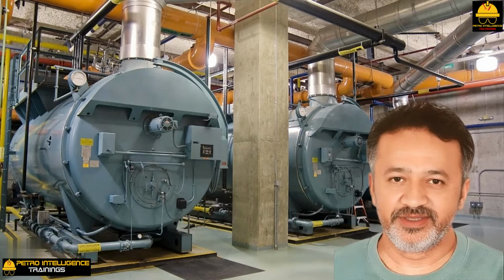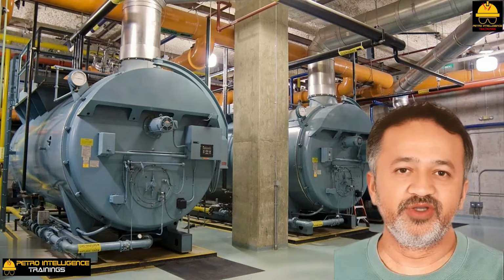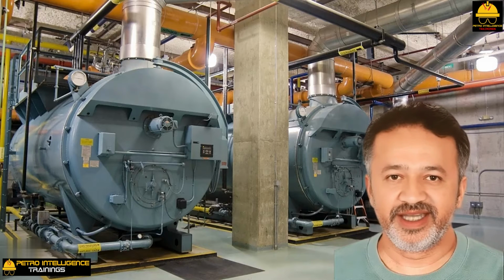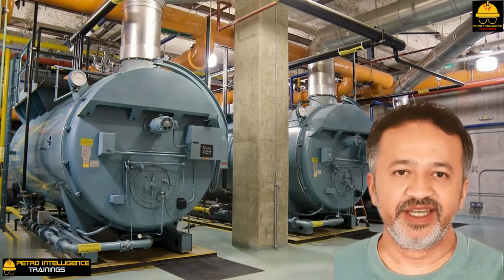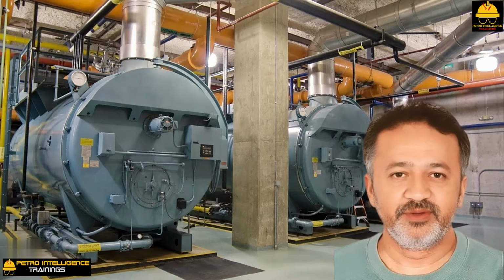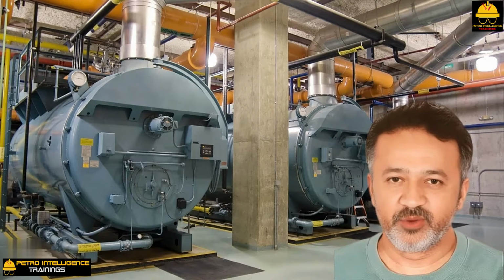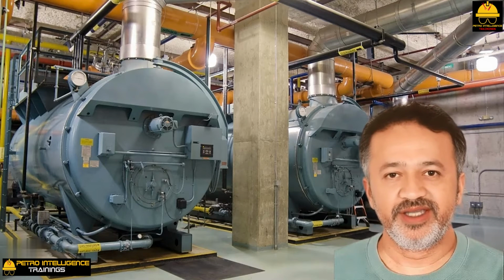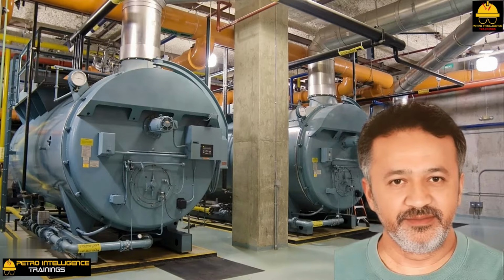Very approximately, 10% of the cost of steam generation could be saved by recovering the condensate. The condensate contains few silicates, thus no blowdown is needed, no chemical treatment or deaeration is required, and no energy that would otherwise be used to preheat the boiler feedwater will be wasted.